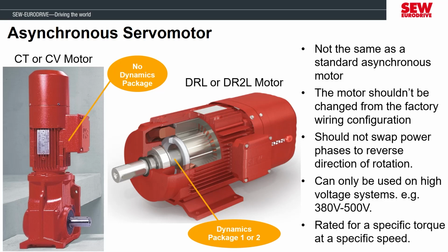These motors will not have a horsepower or kilowatt rating on their nameplates. Just like permanent magnet servo motors, these motors are rated for constant torque up to a maximum speed, such as 2100 or 3000 RPM. This is why the nameplate will show a rated torque and a peak torque value with speeds that are different from standard motors.